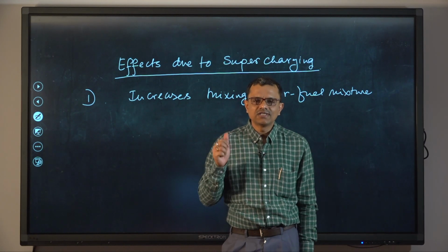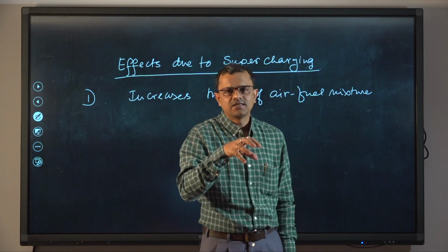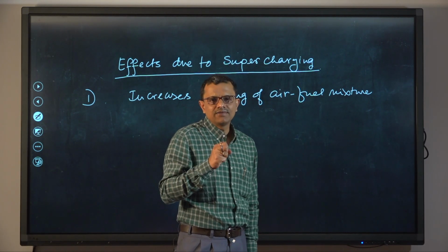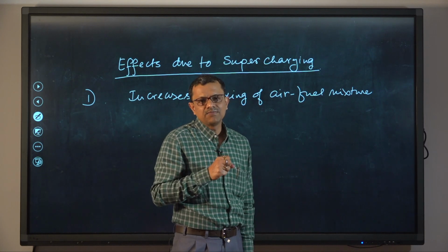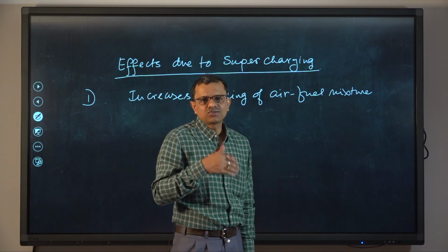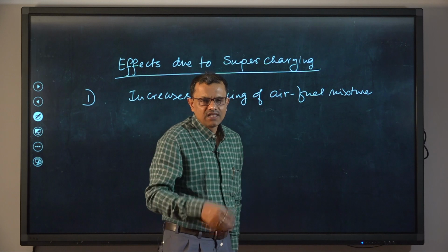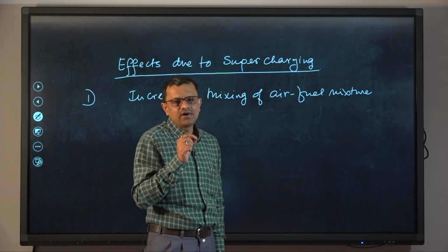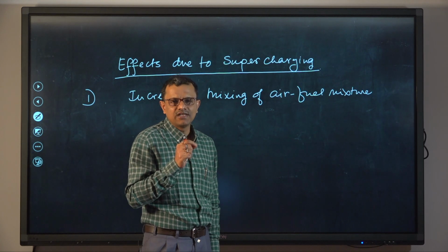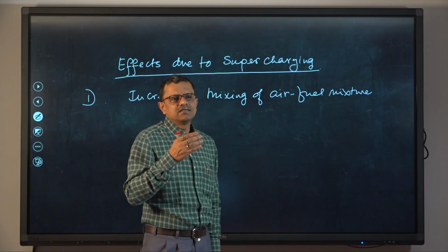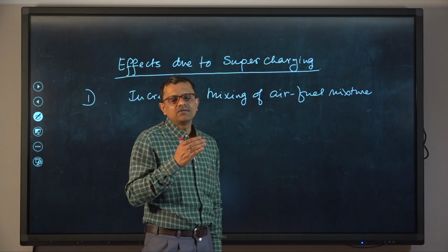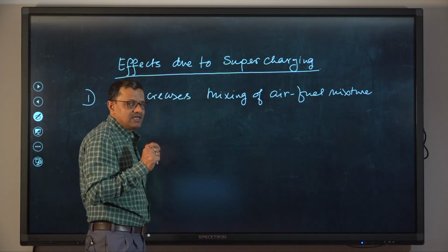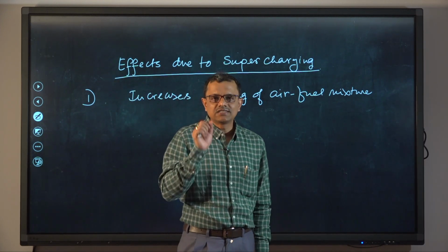We need to ensure that the fuel sprayed into the incoming air stream mixes with it properly, so as to ensure a homogeneous mixture. For that, certainly some chaotic environment should be there in the intake manifold; to some extent, the flow should be turbulent. Now, if we use supercharging, the entire purpose is to increase the pressure.